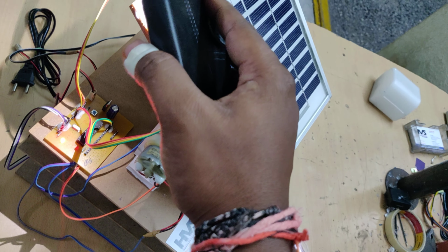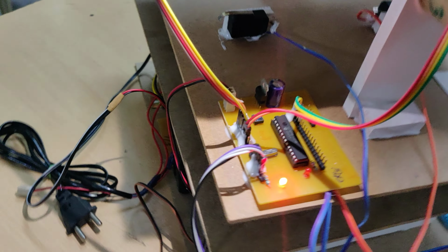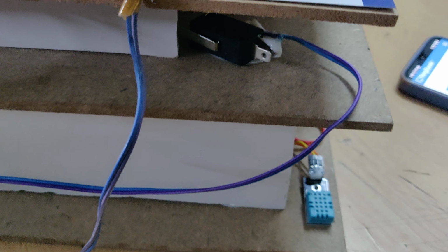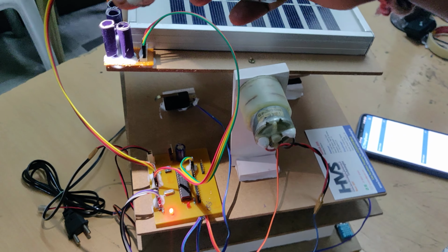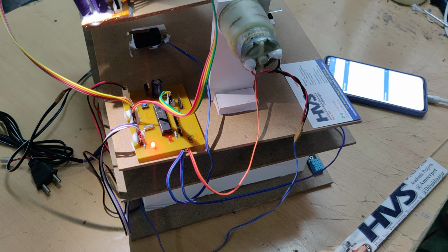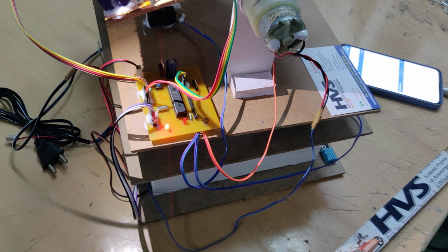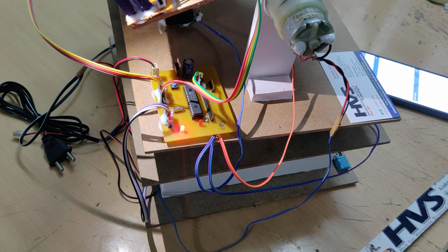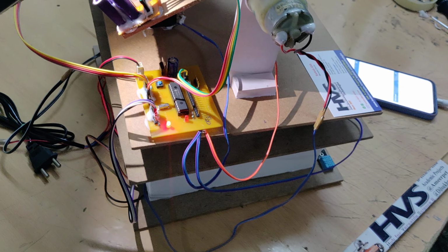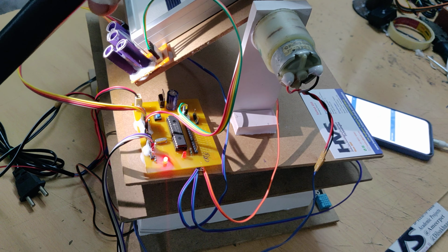So when it is set to the west side, then automatically the 2 DC motors will rotate till the limit switches. There we place the 2 limit switches for X motion and Y motion. There is another limit switch placed on this one. So coming to the interfacing connections, we have interfaced these 3 limit switches at pin numbers C5, C6, C7 of our PIC microcontroller. Right. And 2 DC motors are interfaced through the L293D motor driver. So that was interfaced at C0, C1, C2, C3 pins, and these 4 LDRs are interfaced at the A0, A1, A2, A3 pins directly.